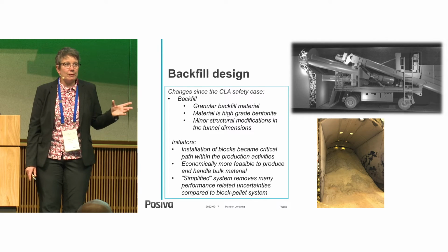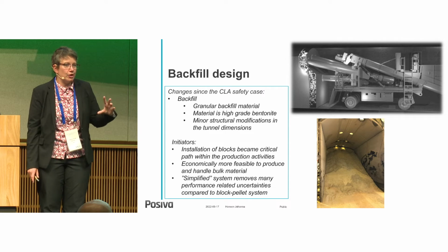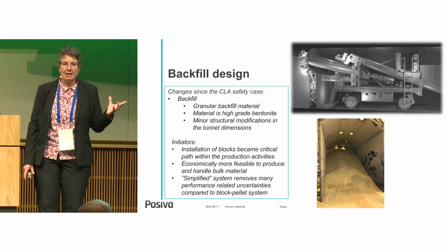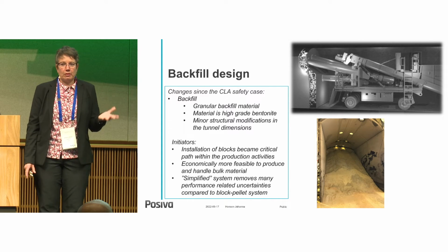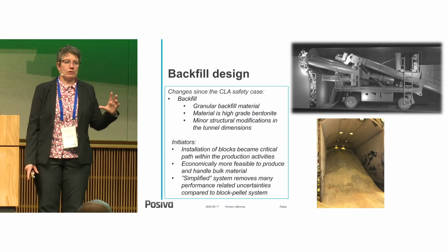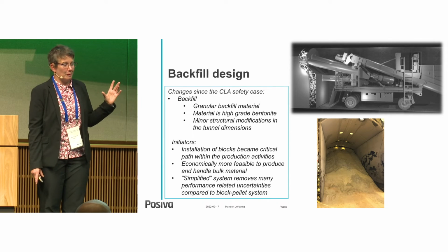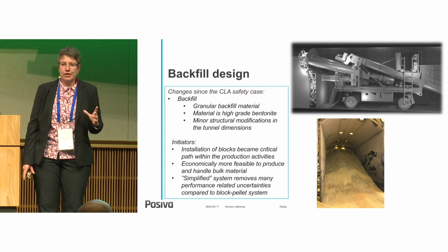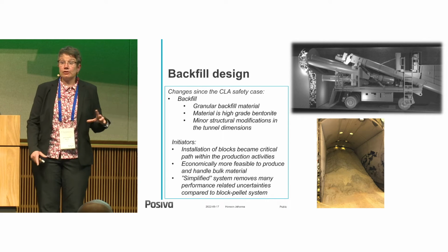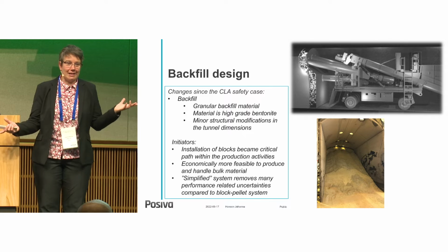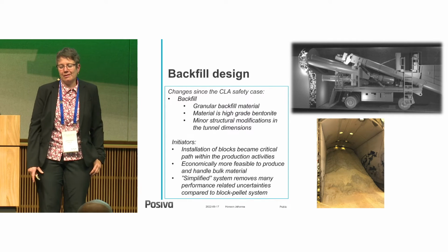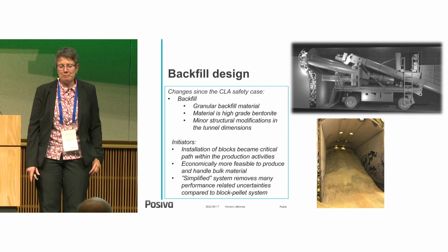The fact was that we did note, when we were doing the full-scale in situ system test, that our backfill blocks and pellets for our needs and for tunnel dimensions were not the best or the optimal solution due to capacity and due to some other topics, which does not exclude that someone else could use that well, but that was from our operating point of view.